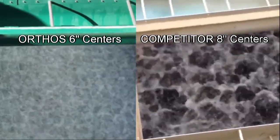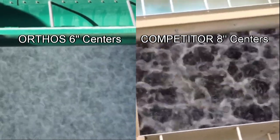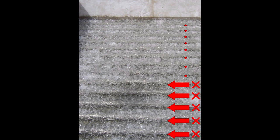One may easily see the distribution difference between nozzles on 6-inch centers each way versus 8-inch centers, as well as the relatively poor air scour distribution of the folded sheet metal and wedge wire screen lateral systems that are 12 inches apart.